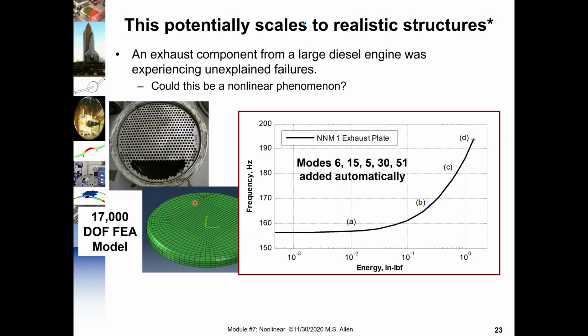And so even with a relatively large finite element model like this, we're able to do the same kind of calculation and tell our employer how much the frequency will change over the range of vibration amplitude you expect to see in service. If the change in frequency is large, then you might need to account for it. If it's small, we can approximate it as linear.